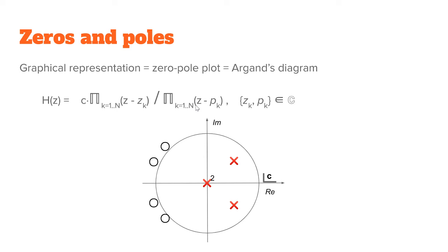This one here, where omega is pi, corresponds to sampling rate over 2, the Nyquist frequency, the highest frequency you can represent. In the analog case, the highest frequency is at infinity or minus infinity, where the low pass filter output goes to 0. So basically this starts to make a little more sense.